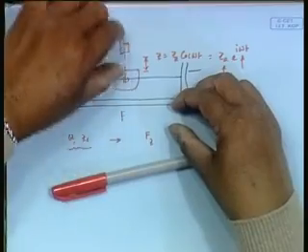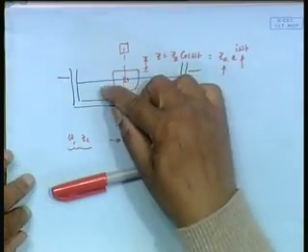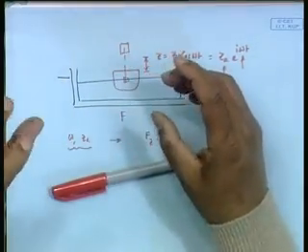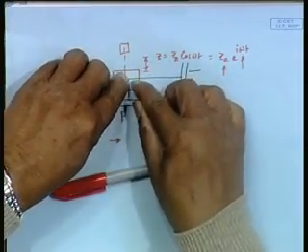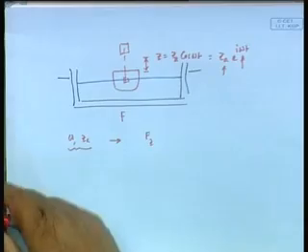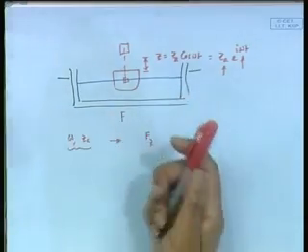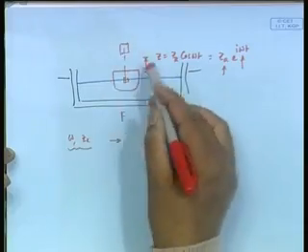These are my input, but this is the interesting point. See, I am doing that, of course, fluid sets up a pressure field here. So, therefore, I have to work against the water. So, there is a force coming, and that is what I measure by an equipment here. So, I measure the force. Now, from this I can find out, you see, this is called forced oscillation test. I can find out the added mass and damping.